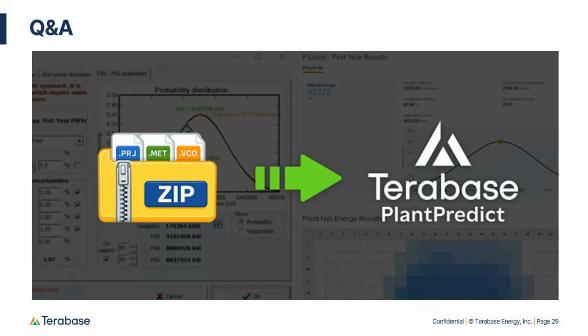So in PlantPredict, if I'm losing 20% and 20% again, I know that these two losses, if they are in the same group, are the same number of megawatts. Whereas in PVsyst, if you lose 20% and 20% again, in absolute value one is 20% higher than the other: one is going to be 20% absolute and the other is going to be 16% absolute. So it's just a question of how you want to compare these buckets and how much there is in one versus how much there is in the other.